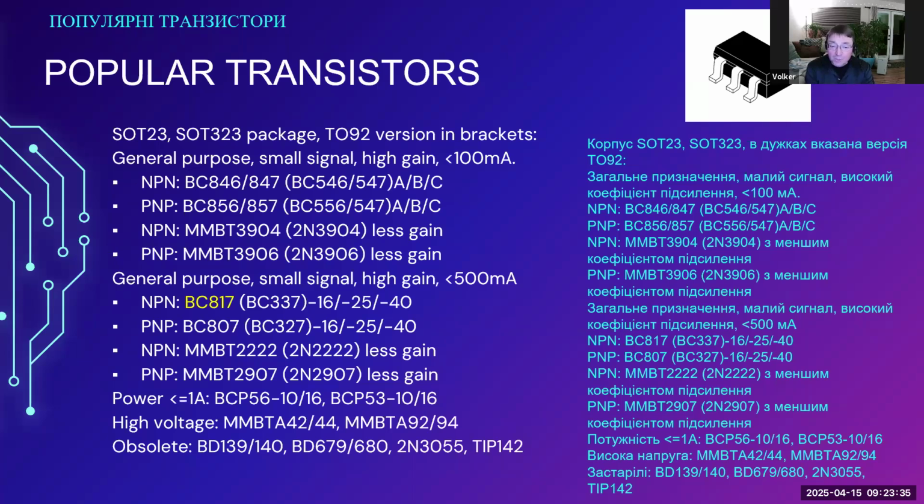There are higher voltage types, for 150 volts, for 300 volts. Generally, it used to be always easier to manufacture bipolar junction transistors for higher voltages. 300, 400 volts was not very difficult. So those are older devices. It used to be very hard to create MOSFETs for higher voltages. That has changed. But these MMBTA42, MMBTA92, those devices have been on the market for a long time.